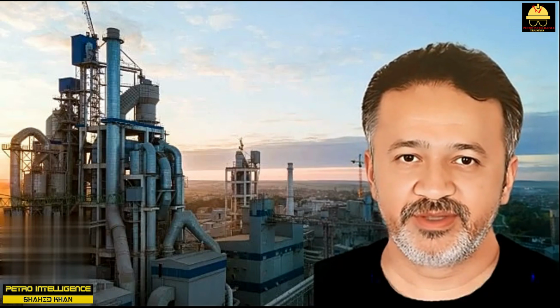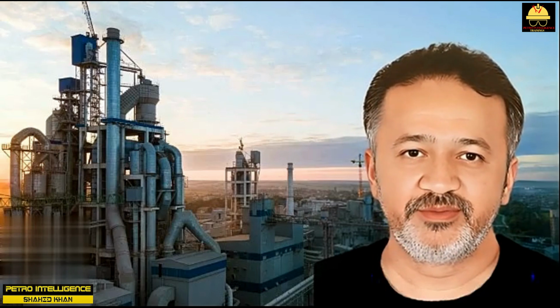This happens when the controlling resistance to heat transfer is shell-side fouling. The fouling deposits get trapped between the tiny fins. This acts as an insulator between the shell-side fluid and the surface of the tubes. In severe shell-side fouling services, I have replaced fin tubes with bare tubes and doubled the heat transfer duty on the exchanger. In summary, low-fin tubes may be used to advantage only when the controlling resistance to heat transfer is the shell-side fluid itself.